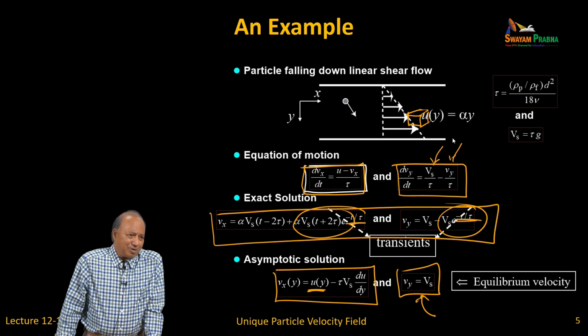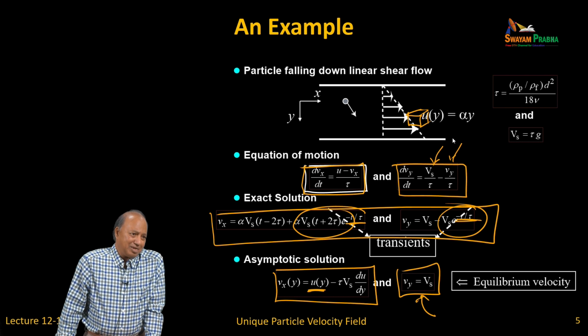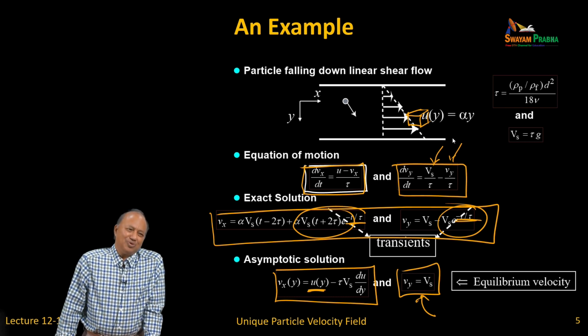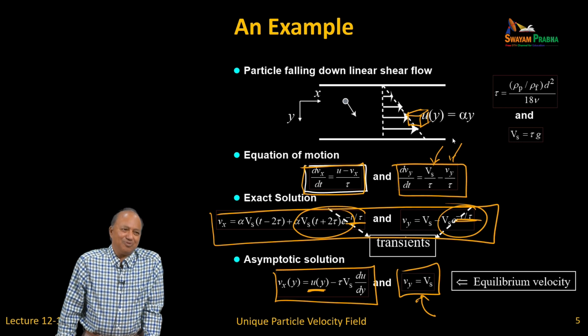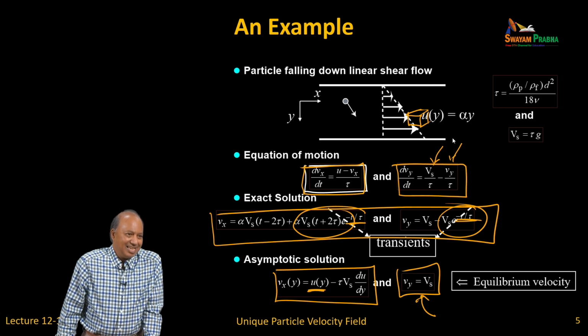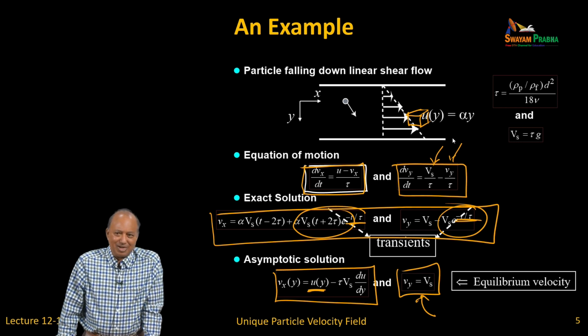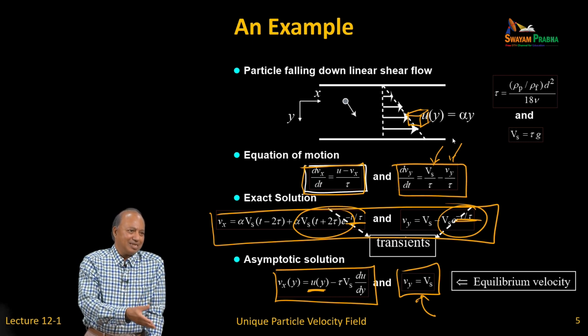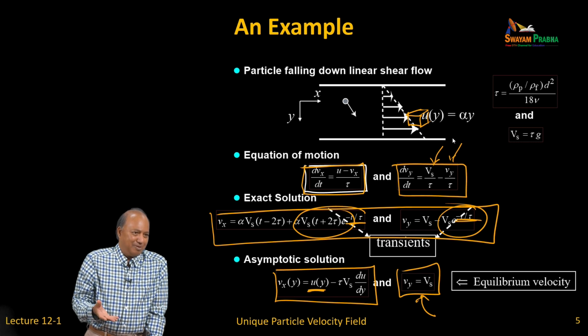Now, if Stokes number is 10 to the power minus 2, say for example you are tracking sediment particles which are 100 micron in a river flow, that's so small, you don't even need Euler. You can do much cheaper than that. And that is what I wanted to bring to your attention, that there are many different methods and you want to use the best one that is cheapest for your job. Okay.